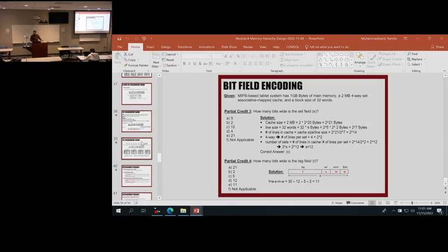But we always design it for the worst case. How do we fix this problem? We design it for the worst case. That's how many clocks it takes to read the data. So when I told you that when we have large sizes of memory, it's going to take more time to access data, this is one of the reasons. Besides having this large peripheral circuitry, the bigger the memory is, the worse the worst case that you want to design your system for gets. Right? But this is a lot of electrical engineering involved. We do research on that in my lab, but this is not a computer architecture thing, it's a computer circuit thing.